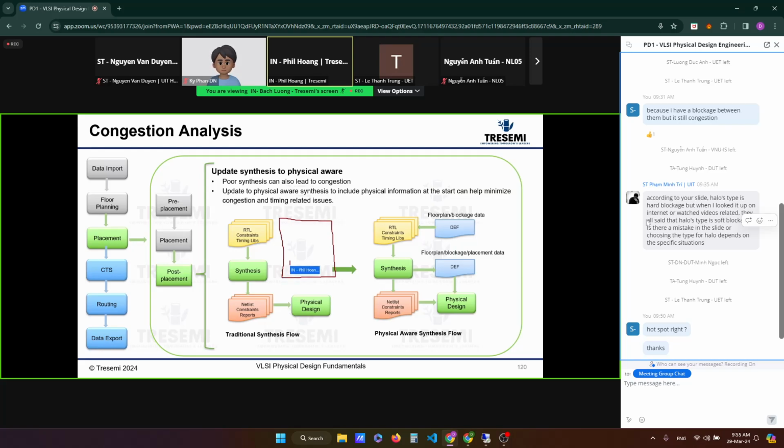So if you have a driver driving from this corner of the design, and you have, say, a memory that's been placed here, at a fixed location, and based on the wire load model this driver is only driving this one single memory, so in wire load models, a fanout of one gives an RC equal to fanout one times some factor, and this factor depends on the size of the block that you're analyzing.